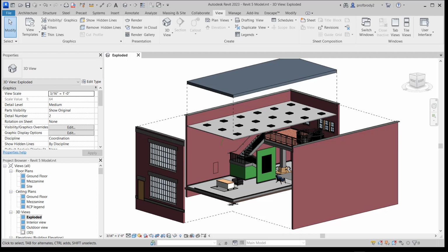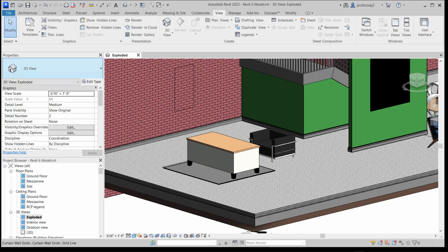Revit is a building information modeler, or BIM, and the thing which puts the I in BIM is the information, and that is defined in Revit as parameters. And parameters are basically different properties of the elements within Revit, say the thickness of a wall or the material on a desktop. Before we go creating our own custom parameters, let's take a look at one of the objects in our model, this desk, and see what kind of parameters it has.